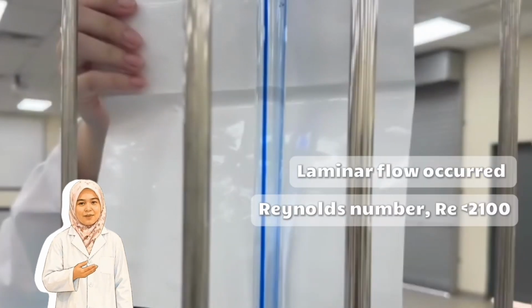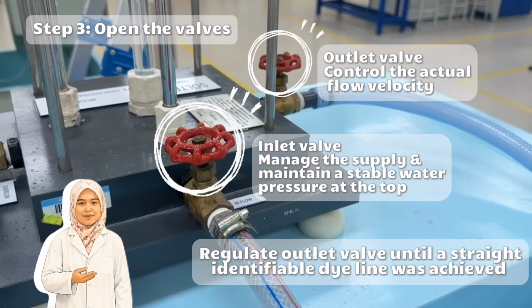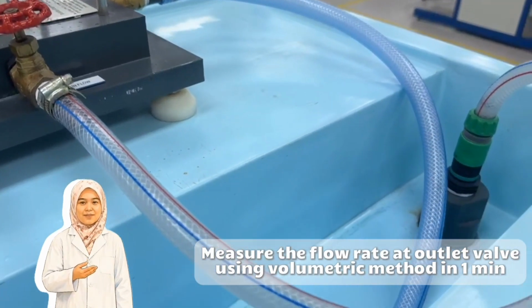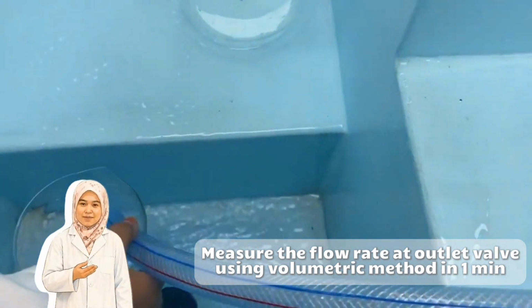Thirdly is laminar flow. So here we can see the laminar flow occur, where the inlet valve V1 and the outlet valve V2 were regulated until a straight identifiable dye line was achieved. This indicates laminar flow, where the calculated Reynolds number was less than 2100. The flow rate at the outlet valve V2 was measured using a volumetric method.